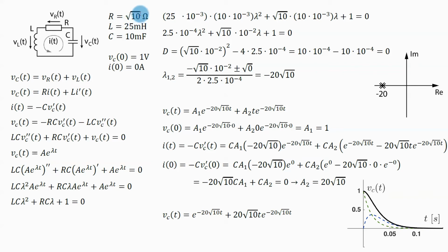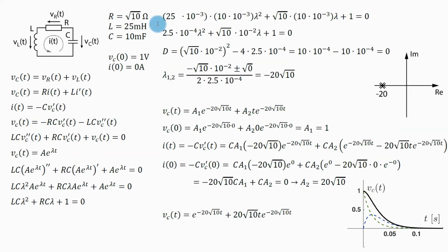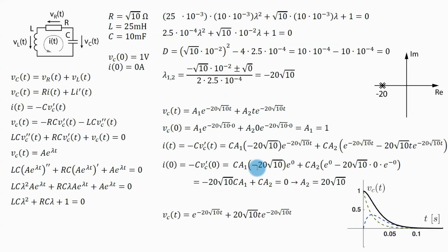get to this circuit and not to end up with oscillatory response is exactly this value, which gives me that critically damped response. If I make this resistance smaller, then I will get this case number 1 where I have oscillatory response. If I make this resistor bigger, then I will get my last case where I have that overdamped response which takes a long time to stabilize. That critically damped response lives in between these two and it gives me the fastest discharge, that is the fastest stabilization of my circuit.